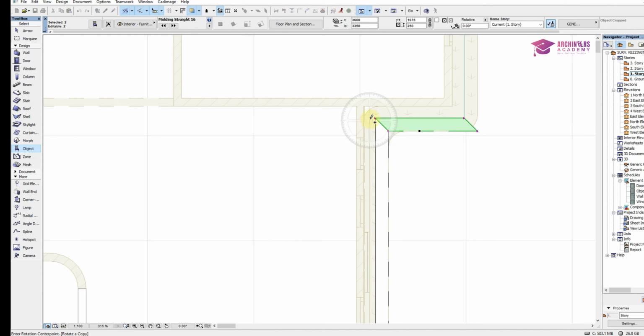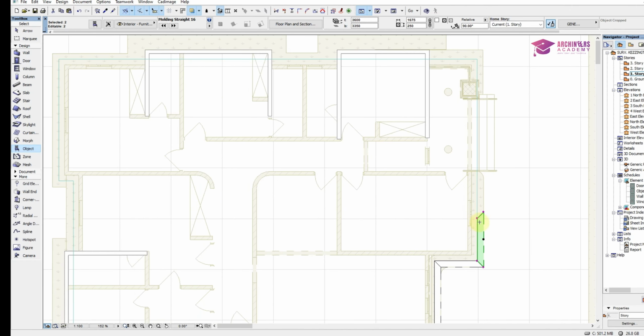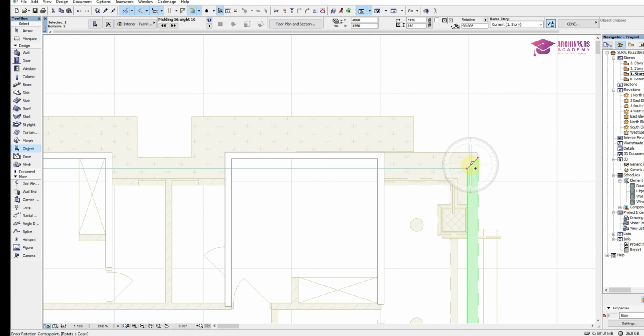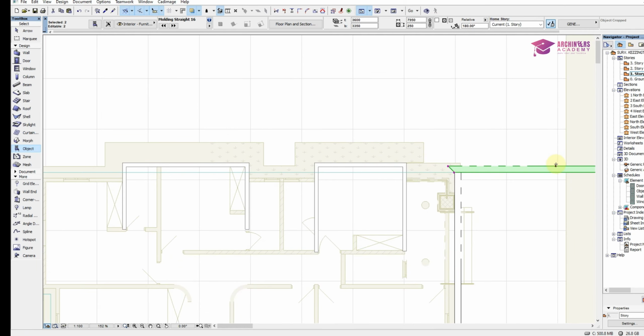Control Shift E. So once I'm done putting all the concrete fascia on this roofing height, I will now do the same for the other roofing height. So Control Shift E, ensure that the black bullet is rotated to be outside always. You can see it's always outside.